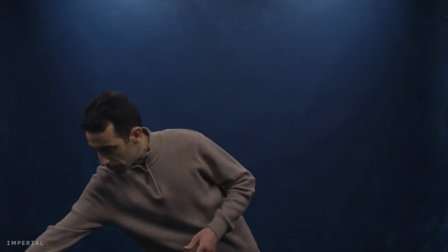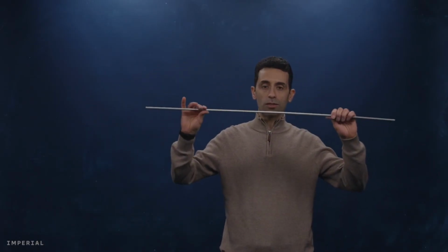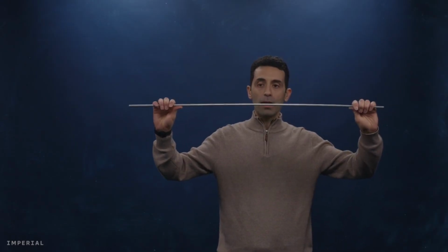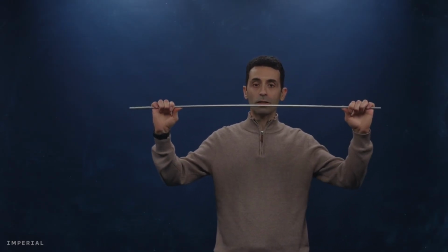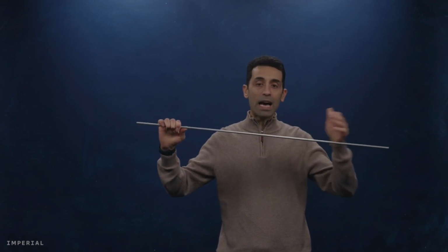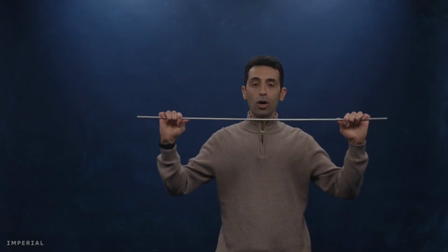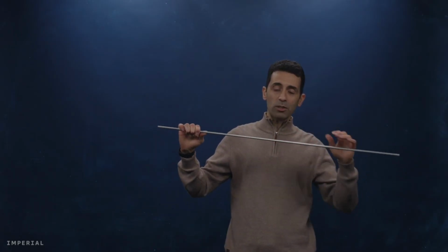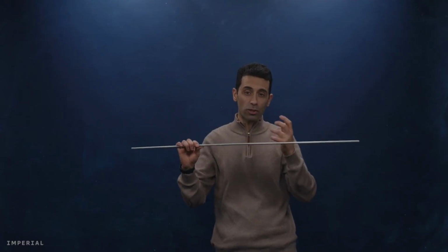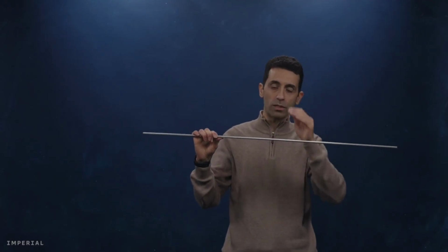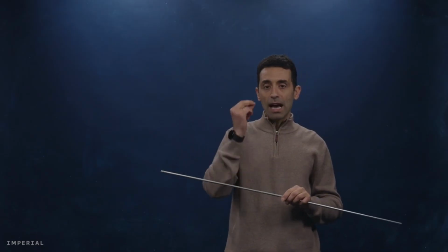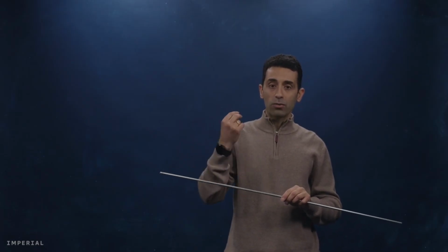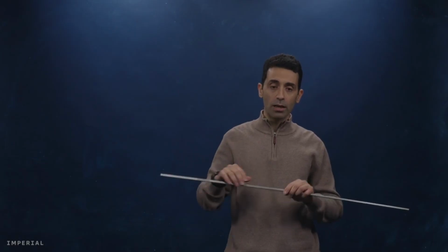So as I mentioned in the beginning, 50 to 90% of all mechanical failures are due to fatigue. So fatigue, you can imagine, applies loads on a structure like this bar, this beam, continuously, and potentially reverses the direction of the load. But this can happen for thousands, hundreds of thousands of cycles until fracture starts. Especially, fracture starts in materials and structures where there are stress raisers. So if there is a notch, for instance, that is where there is a stress raiser, and that is the location where a crack and fracture can initiate from under cyclic loading.